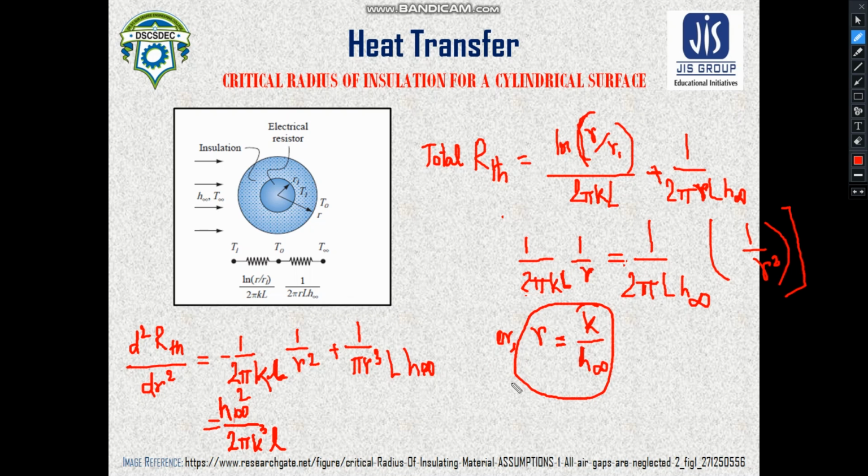It is an optimum sense, which gives you the understanding that this is the maximum heat transfer rate which can be achieved if we go on applying the insulation material layer by layer. Okay, so it is quite obvious, and I hope that you have understood the clear concept of heat flow being the maximum at the critical radius of insulation.